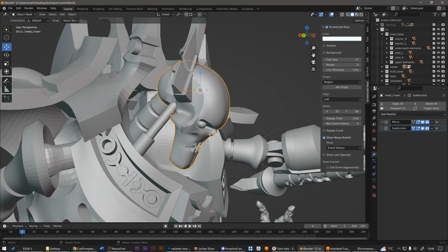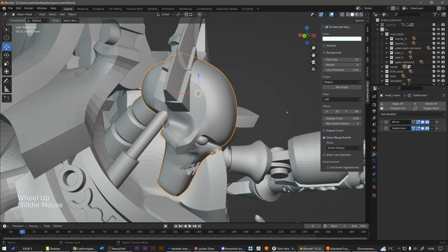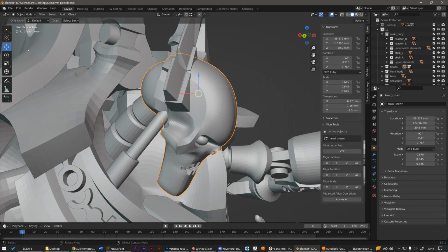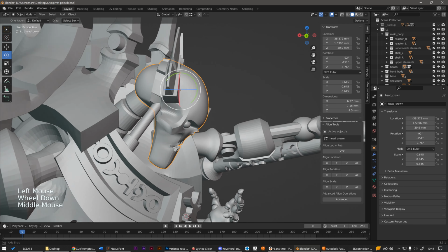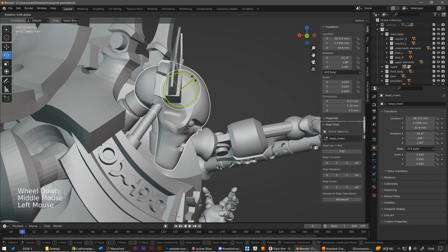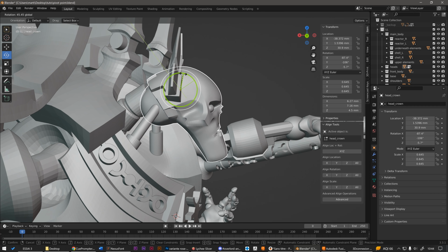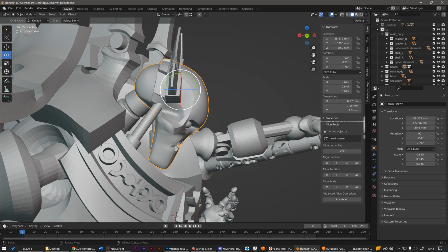So the position of the origin corresponds to the XYZ location coordinates we can see in the Object Properties panel, values that can also be found in the Item tab. And when we rotate something, the rotation is done around the object's origin. This is why we have seen that it's better to place an object's origin where we want it to turn around, on a joint or articulation for instance.